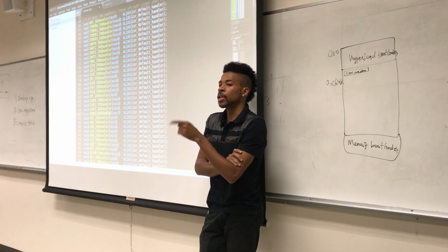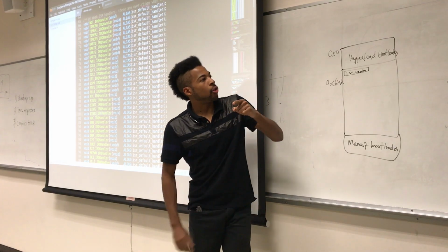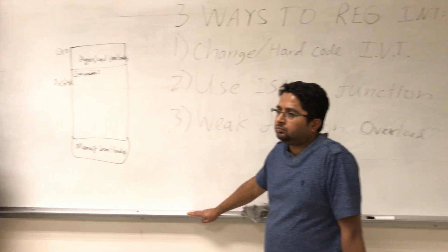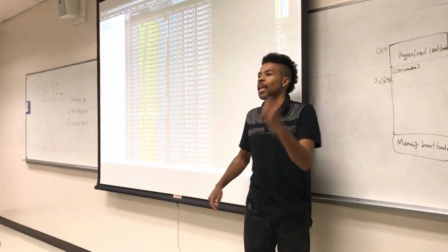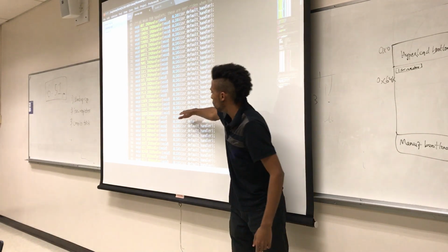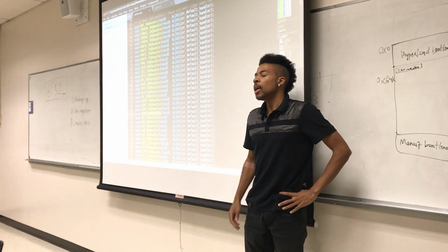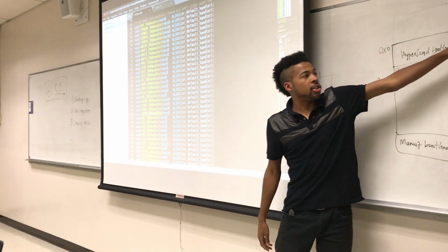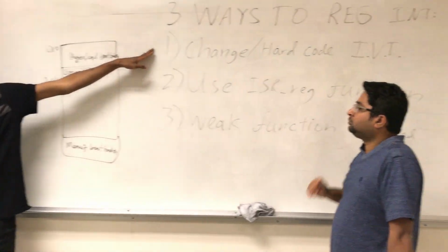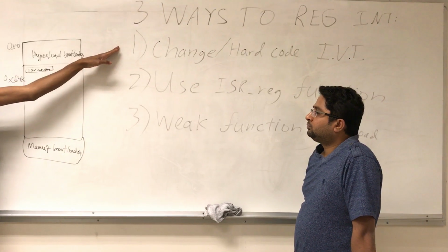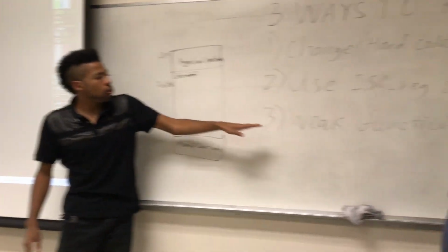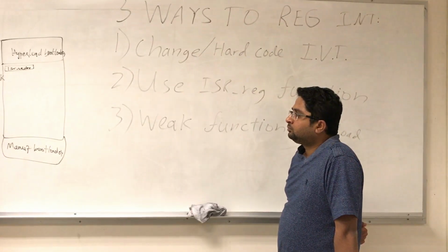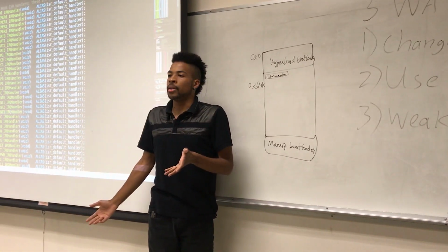It could be, but I would highly suggest that you use this method here. Using the ISR function. There's the ISR register that's inside of the startup page. You can use that to just give it any arbitrary function for that particular interrupt service routine. It's more dynamic. I actually think that changing the hardware interrupt vector table is the worst way to go about this because you can mangle up your startup.cpp. You pretty much should not touch it. You can do the weak function overload. There's no problem to that, but